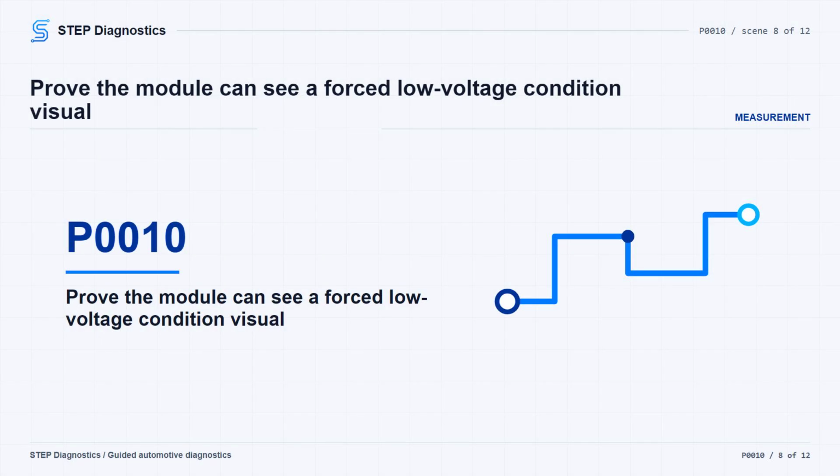If the low voltage test status is OK or not run with the solenoid commanded on, connect a 3A fused jumper wire between control circuit terminal 2B and ground. Command the solenoid valve on again. Now the scan tool should show the camshaft position actuator solenoid valve control circuit low voltage test status as malfunction. If it does not, power down, remove the jumper, disconnect the engine control module connector, and check control circuit continuity.